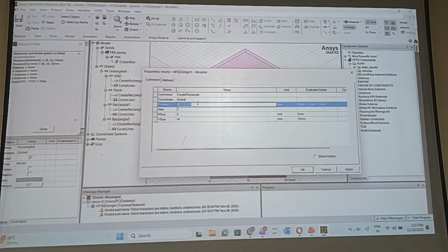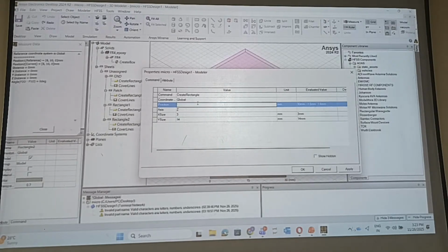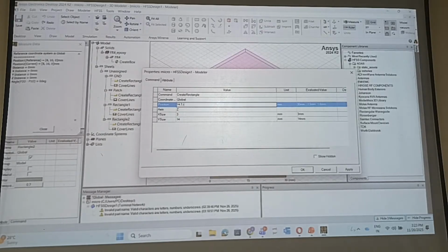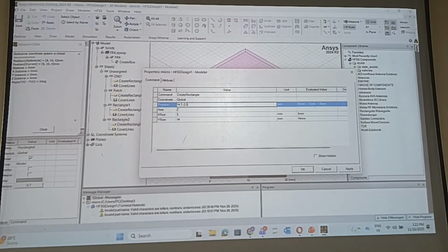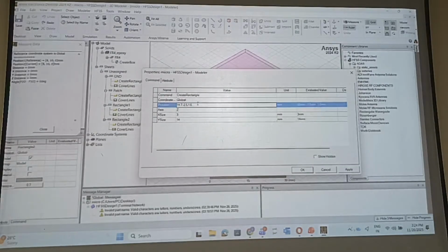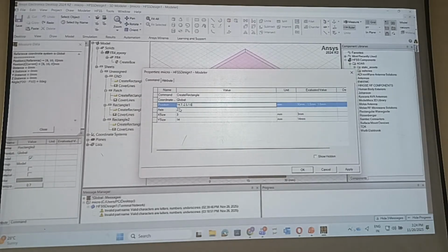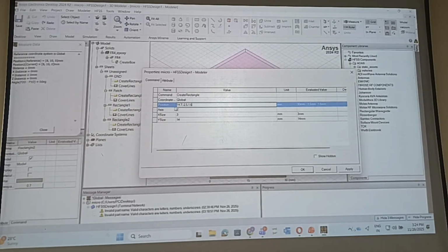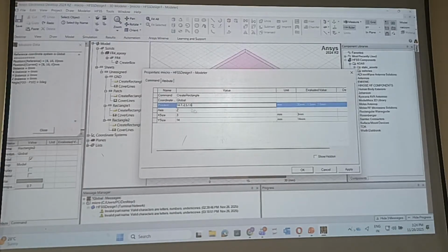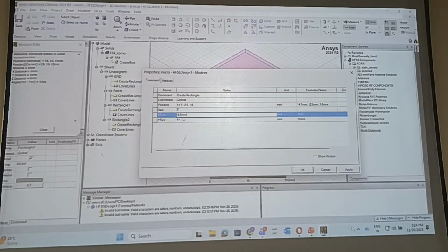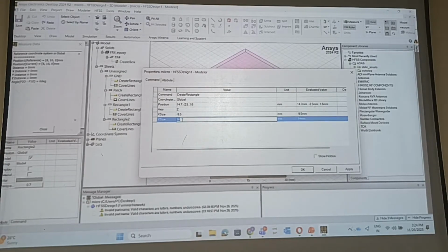Positions need little modifications. Positions are 14.7, comma minus 2.5, comma 1.6. Once again I'll repeat. Its positions are plus 14.7, minus 2.5, comma plus 1.6. We are along the z-axis. X size is minus 9.5 mm and y size is 5.